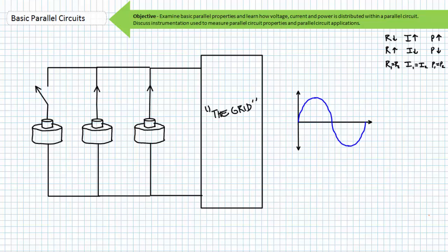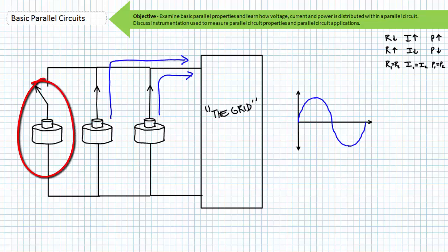Let's think on a grander scale and talk about large-scale generators placed in parallel and something called generator synchronization. This example makes use of some obvious oversimplifications, but consider a hydroelectric dam with a number of turbines, some operating and some at the ready. Hydroelectric dams are neat because they represent both reliable base and responsive peaking power, all based off of renewable energy. A given number of turbines can operate as a predictable base. As demand increases, additional turbines are brought online in parallel to meet peak demands.